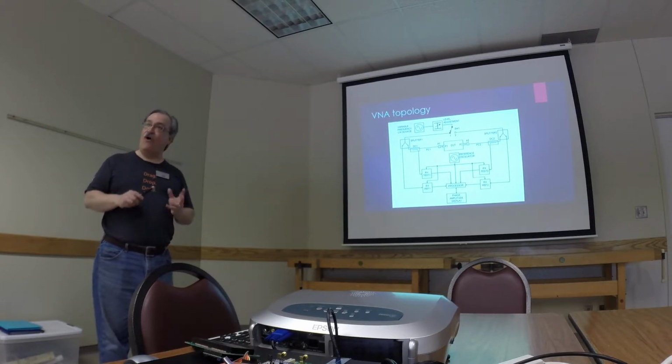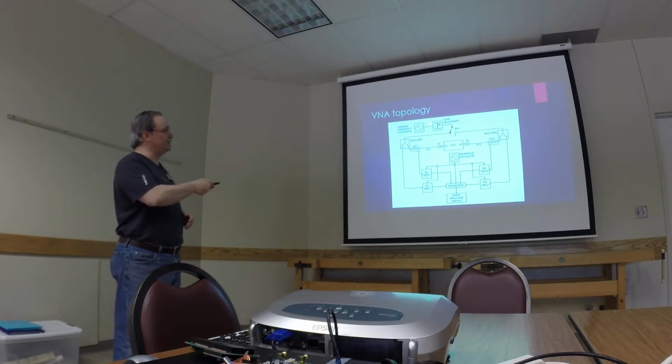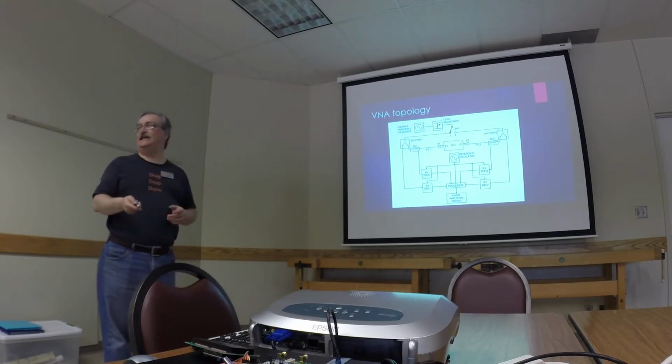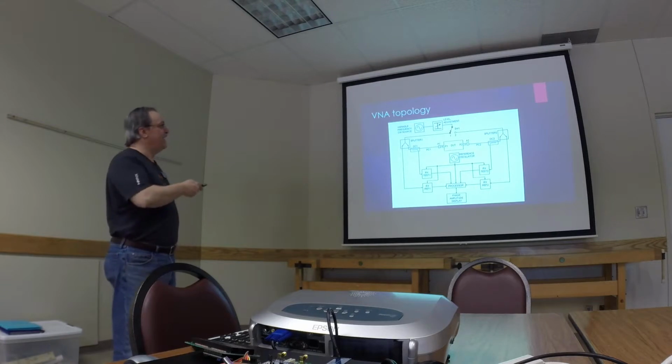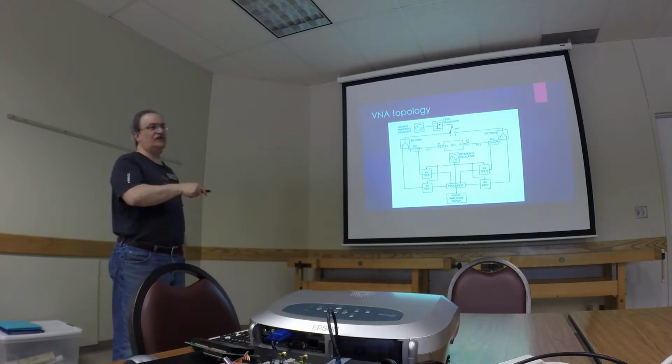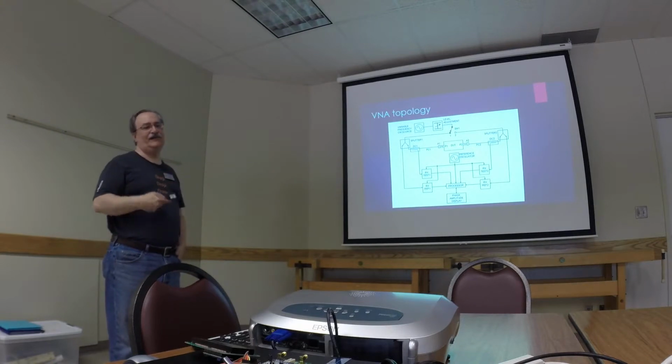You do have to calibrate a VNA, you always do, so you need to make sure that that CW source, which is typically a DDS, is on frequency as close as possible, okay? And you have to make sure that the reference oscillator as well is in sync with that. Now, typically these can be the same circuitry, but one that'll sweep and one that'll tick back and forth.